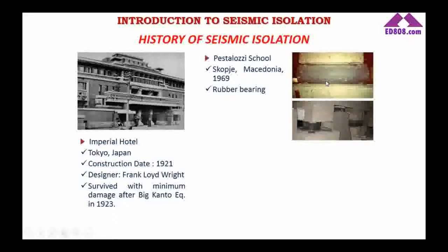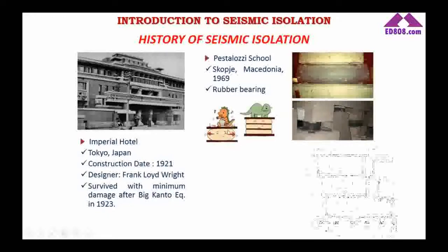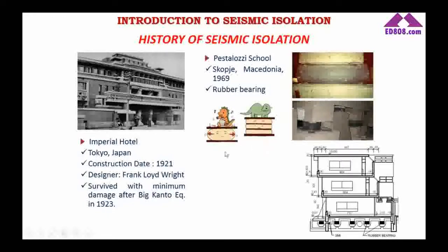because there were no steel shims. The vertical stiffness of these rubber pads was not high. It suffered from the axial loads acting on it, because it's like reinforced concrete columns. What you do in a reinforced column to increase the compressive strength is place stirrups to keep the core concrete there. It's very similar. If you do not place steel shims in the rubber, it makes bulges like that.